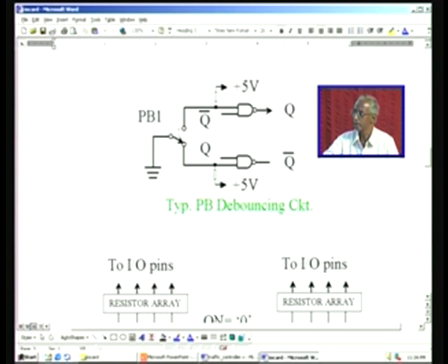And let us see what is the case. This Q bar is connected as the input, just remember it is 1 here, and this is pulled high. So, 1 into 1 is 1 before the bubble, and after the bubble it is 0. That means it is 0 and 1 here. Therefore, we have used the notation Q and Q bar, because if it is 0 it will be 1, and if it is 1 it will be 0. And right now, when the push button is not pressed, you get an output of 0. It is this where we are going to take the output.